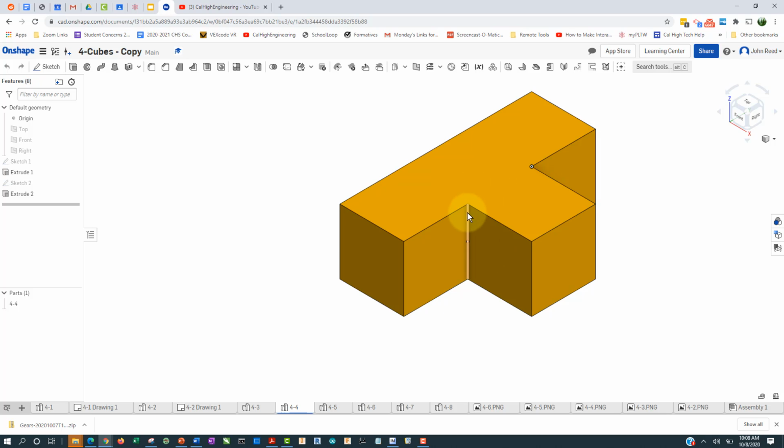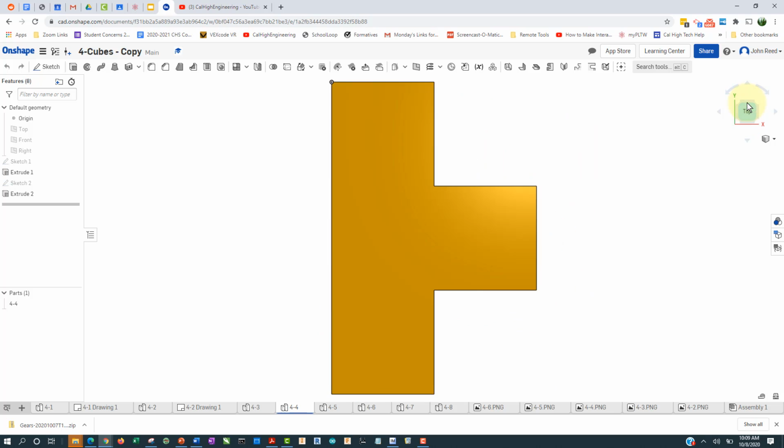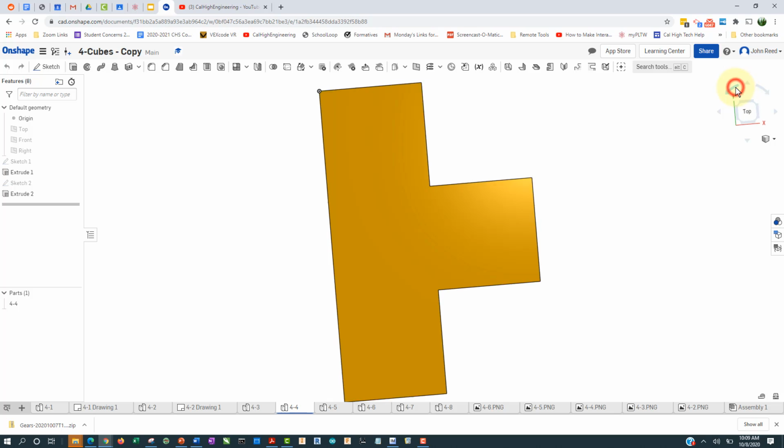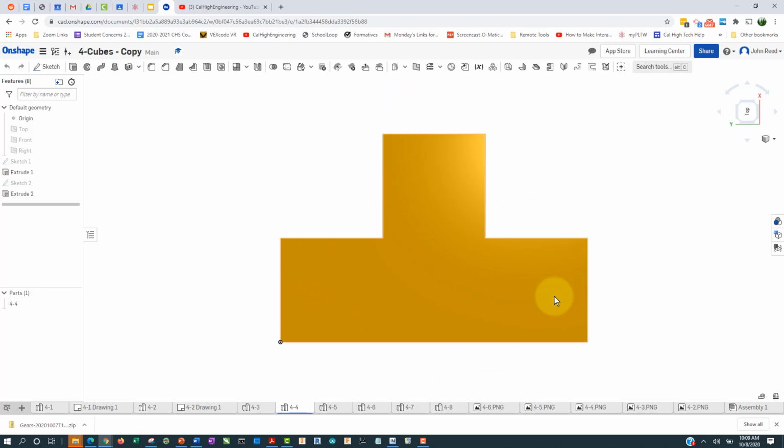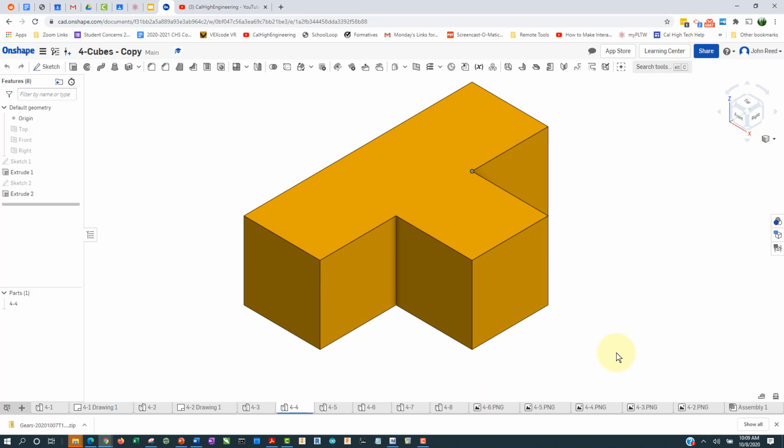So we're going to have to choose a different face or a different view to initially place, and then we're going to have to rotate it after that. So the view that we're going to put in is the top view. So we want it to look like this truncated T, so to speak. But then it's going to be up on its edge, so to speak, and more vertical than horizontal. And what we want to place in there is something that looks like that. So a rotated top view. So that's what we're going to have to do, and here's how you do it.